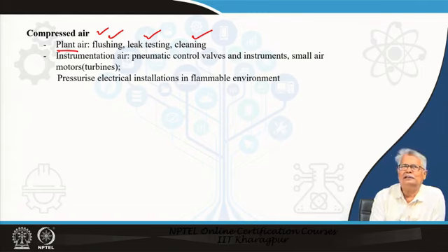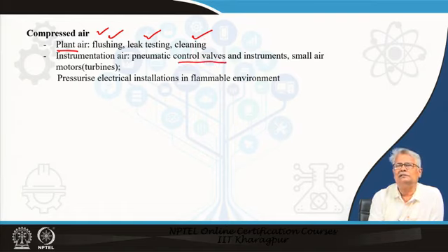Now, you require instrumentation air for your instruments. Traditionally, the control valves have been powered by pneumatic power. The main reason for this is safety. You definitely can have electrical control valves, but the process industry traditionally has been using pneumatic control valves because they do not produce, or do not have any scope of producing, a spark, and they are thought to be very safe. In fact, they are. Quite a few of the pneumatic instruments, in fact all of the pneumatic instruments, require the instrumentation air supply.